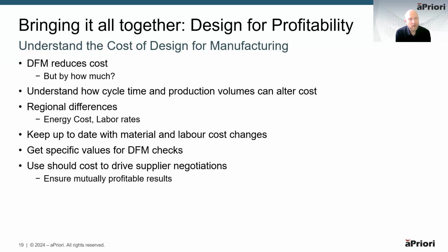And we also, with our design guidance, give you specific values for DFM checks. So we're not reliant on you entering a value. If you tell us that a part needs to be injection molded and it's a particular material, we'll tell you what the draft angle should be for that specific material, for the specific part, for the specific geometry in the specific machine, and even work out what clamp force is required for that injection mold machine. And then all of the data that's generated, we break down all of the processes involved to manufacture that component.